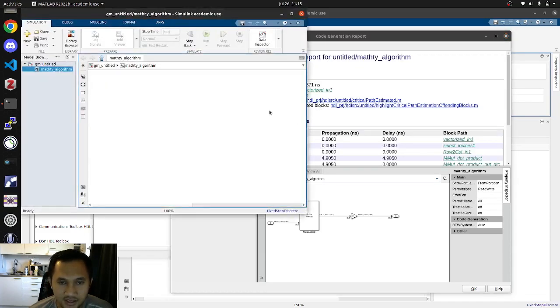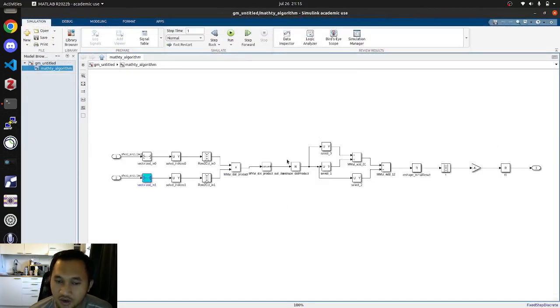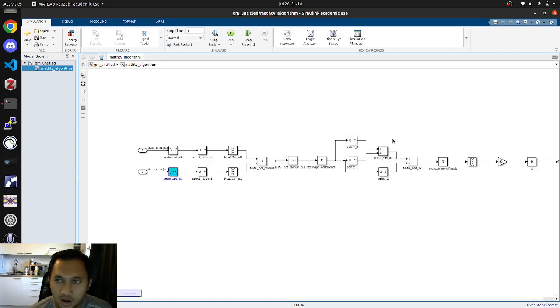We can see the generated model here. It's equivalent, but a bit low level. They convert the matrix multiplication block into this block, and this is the fully parallel one. You utilize a lot of multipliers, which is 27, because we have 3 by 3 times 3 by 3.